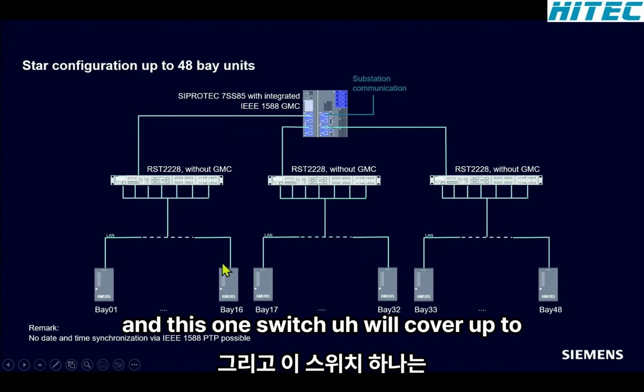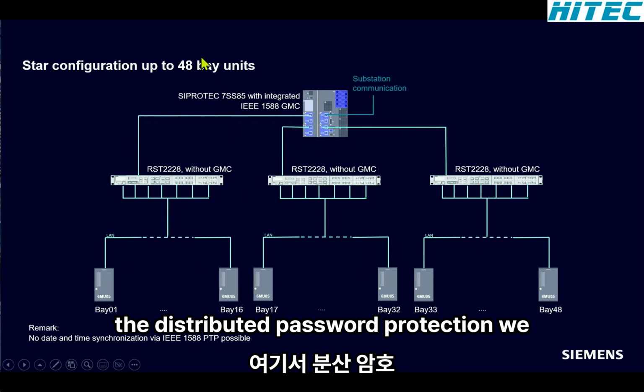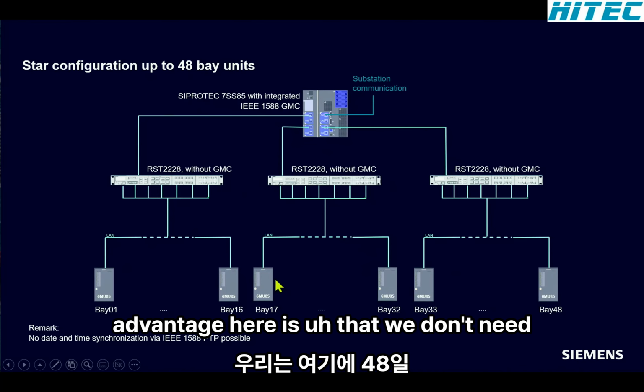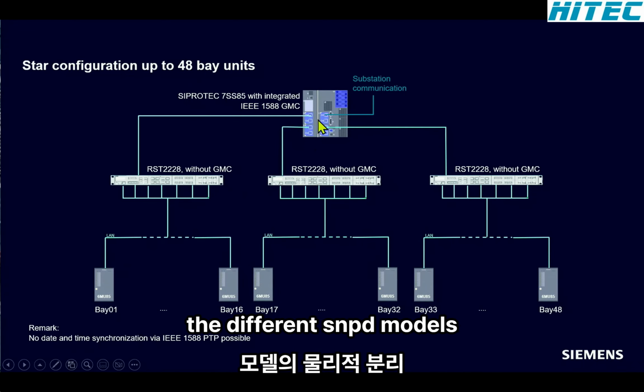This one switch will cover up to 16 bay units. In the maximum configuration of the distributed busbar protection, we will have 48 bay units. The advantage here is that we don't need a VLAN configuration because we have, again, a physical separation of the different Ethernet BT modules.